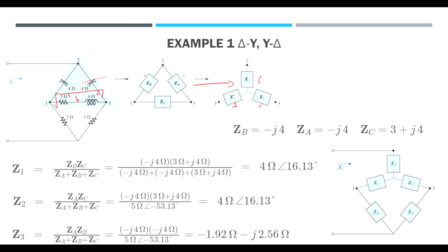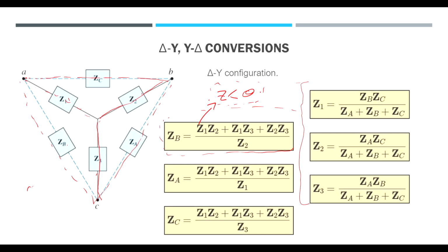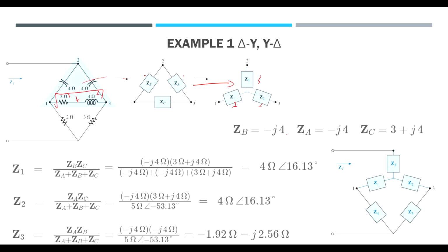And make sure that you do the same thing for the other ones between A and C. So between A and C, we have this point, C connected to A, and then we have impedance 2, and it's exactly what we have here. Once you do that, which remember they're phasors, so be careful how you compute them, you have the equation right here, which in your calculator you can just type with imaginary numbers, positive and negative, the same way you have it here.